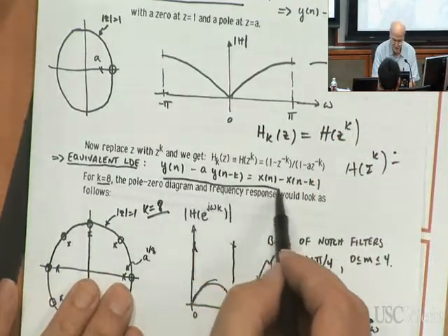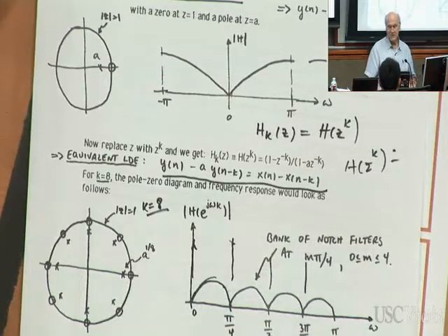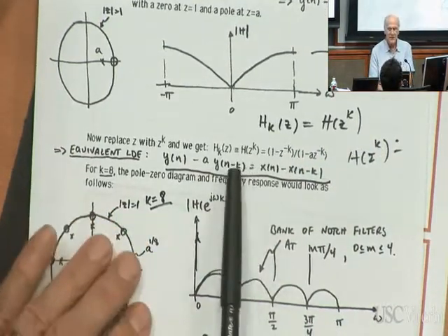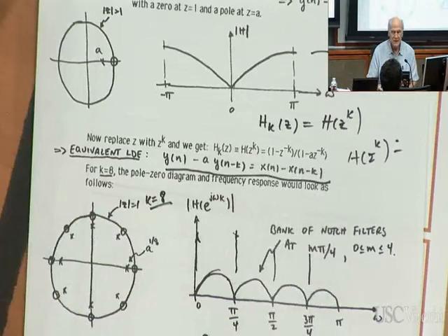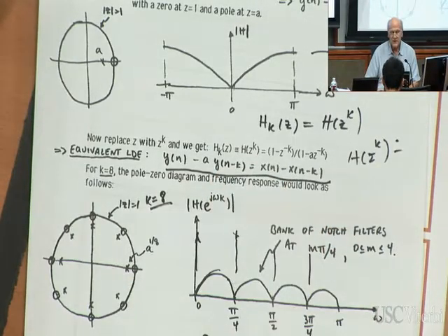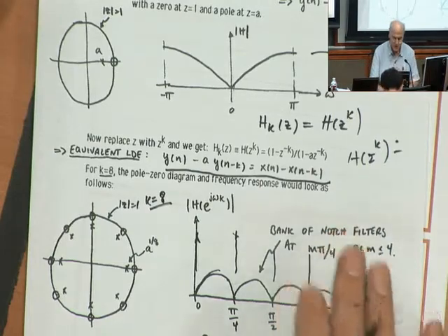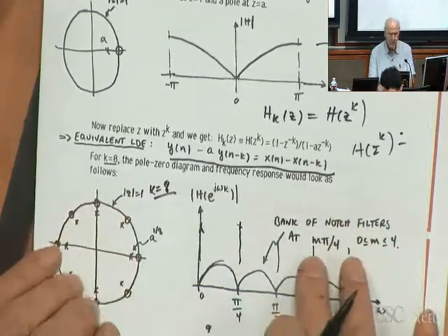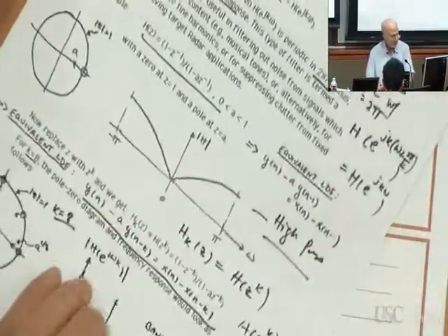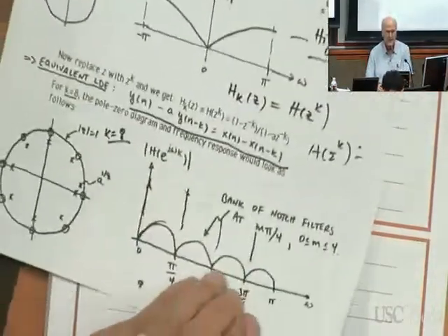Here it is. So actually it looks very similar to the prototype linear difference equation, except you have delays of k instead of unity delays. That's all there is to it. That will implement this comb filter. And you can do that with any filter that you want. It's a very, very useful filter, as you will find out. Now, let me say a few more words about this.